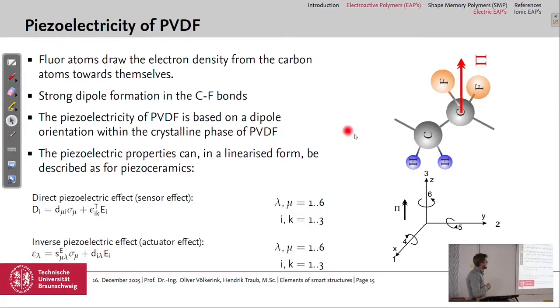And so therefore, the piezoelectricity is based on a dipole orientation within the crystalline phase of PVDF. So the polarization is really in the crystalline regions. And we can describe the piezoelectric properties like we did in the last lecture, again with the small signal behavior in a linearized form.